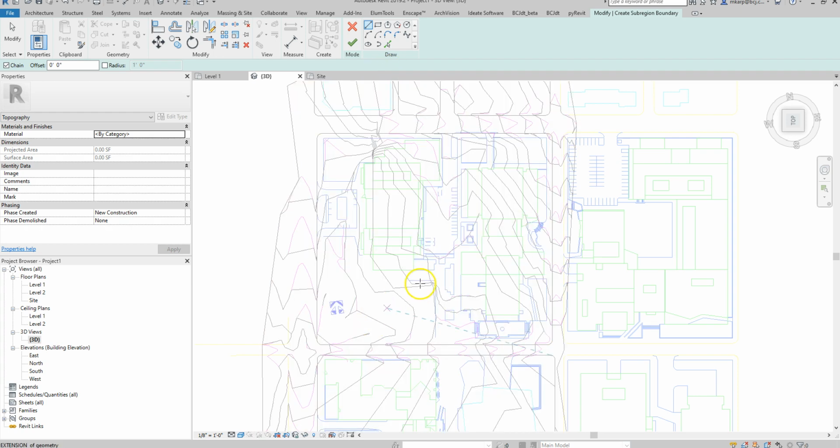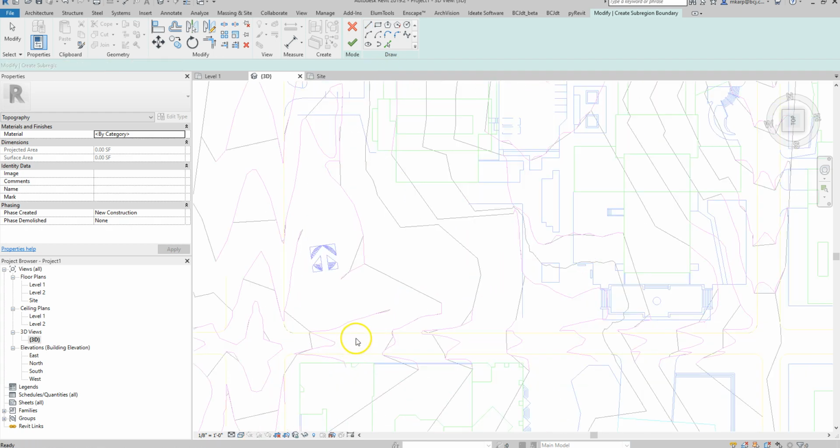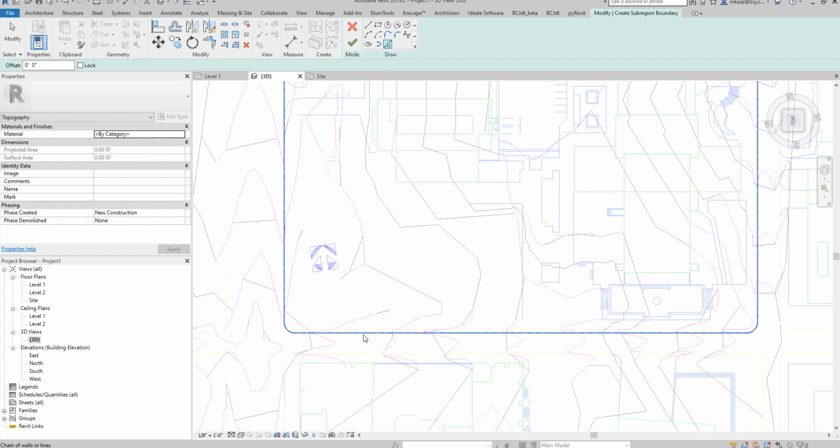And I am going to type WF for wireframe. That gets us to the wireframe. And I'm going to try this. This might not work. Offsetting this 10 feet. And I'm going to use the pick command. Here, hit undo. I'll do that again. Pick command, set the offset here.